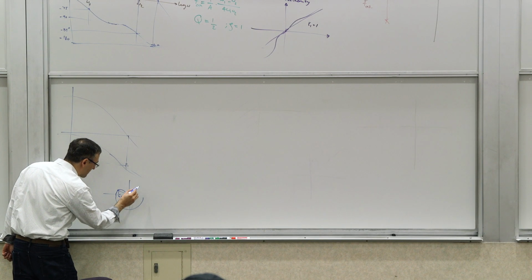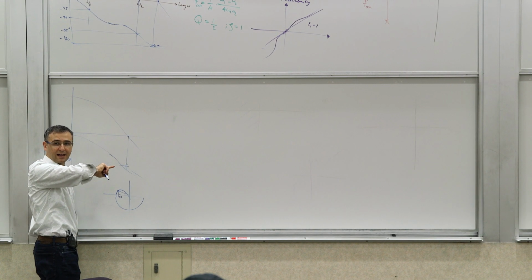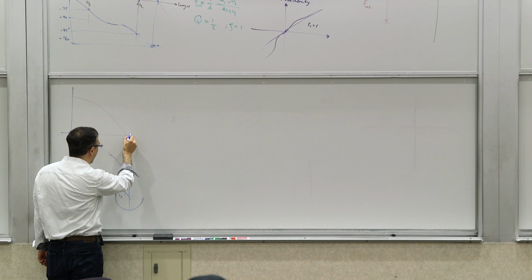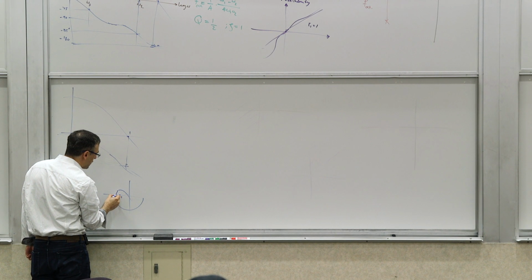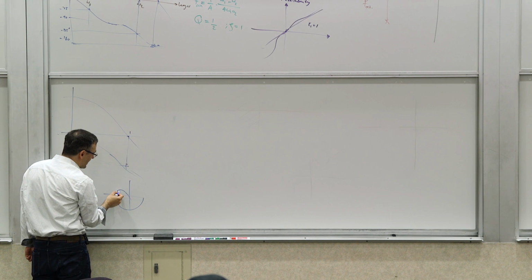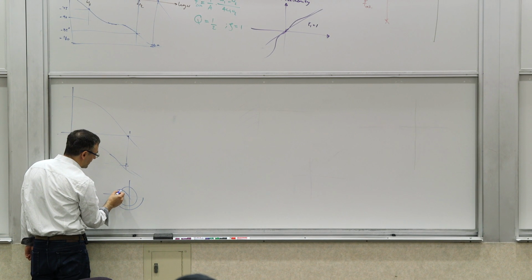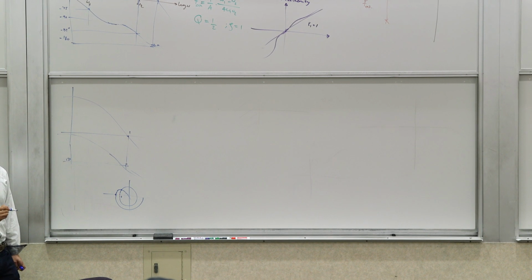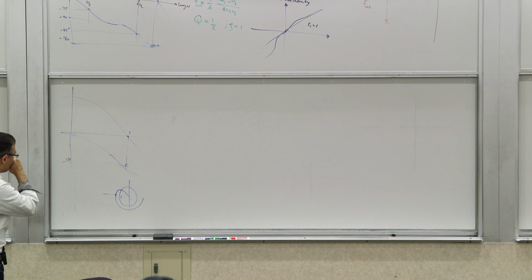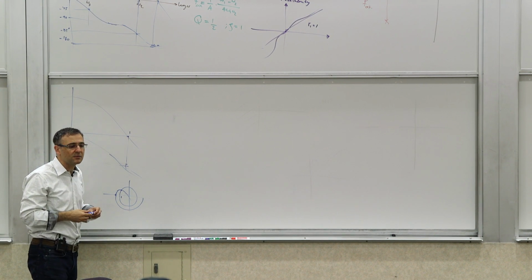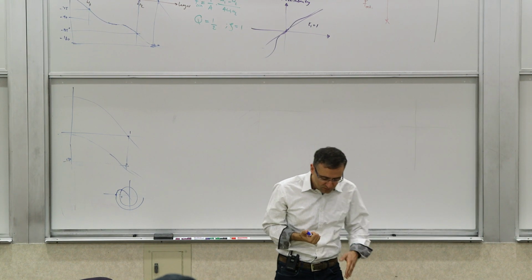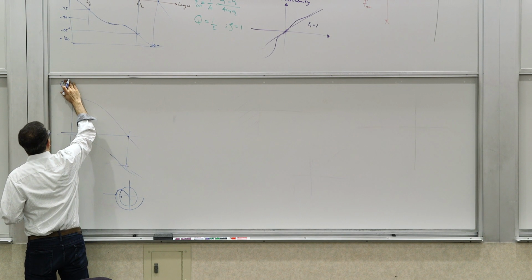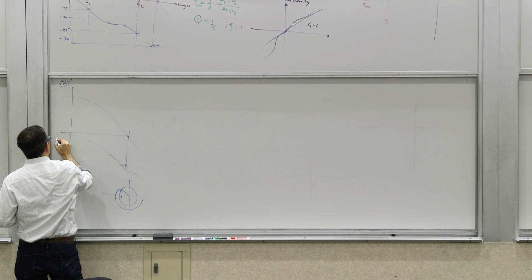Unless you somehow magically came back in like this, and that would show in the phase plot as going back up. So if your phase plot is dropping monotonically like this, and at the point where you have a gain of 1 or 0 dB you have a phase more than -180, it means that if this circle is drawn with a radius of 1, this has happened here. It means you have encircled the point -1. So the question is, what can we do to stabilize this, if this is your loop gain? This is the logarithmic plot of the magnitude of the loop gain and its phase.